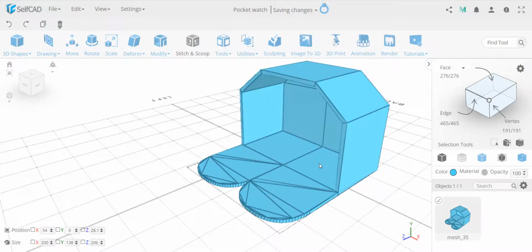But overall, the flow is to either use freehand drawing, which does everything for you automatically, or, if you want to use 3D sketch or copy profiles from anything else, you first have to convert it into a surface. Then converting a surface into a mesh is either add thickness, the default way, or extrusion, and then use either fill polygons or add thickness on it.